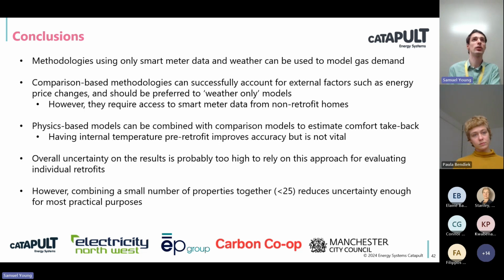The other half of the question is, when you're looking at flexibility, what's the counterfactual that you really care about? What's the baseline where you assume no flexibility has occurred? With general demand response type flexibility, you can get more accurate baselines by looking at recent days and recent weeks than with this approach, where you have to look back and model based on external temperature, what they did a year ago, and patterns in the days of the week.